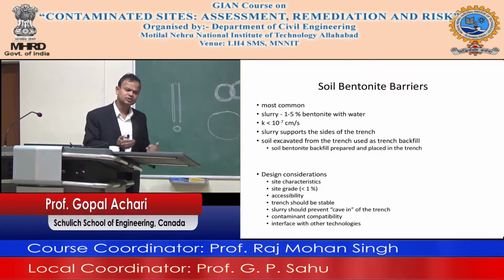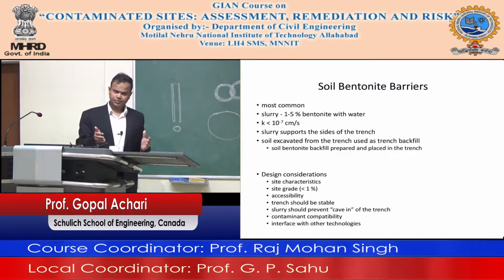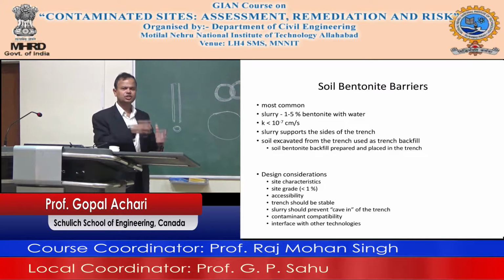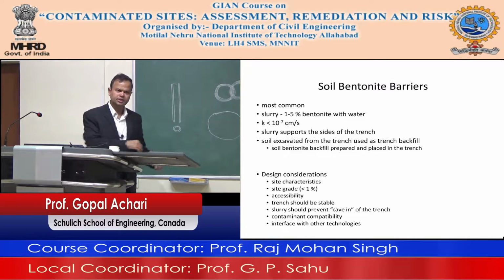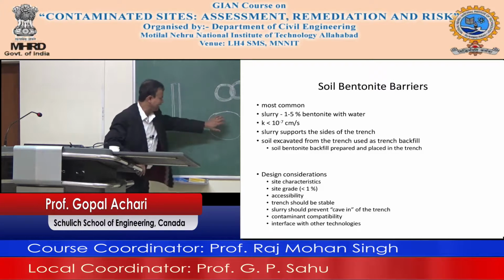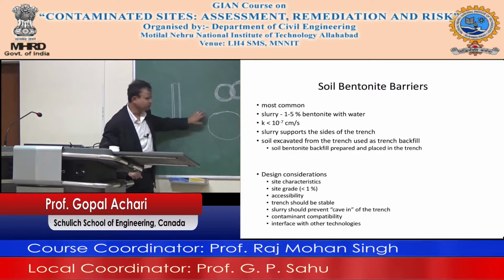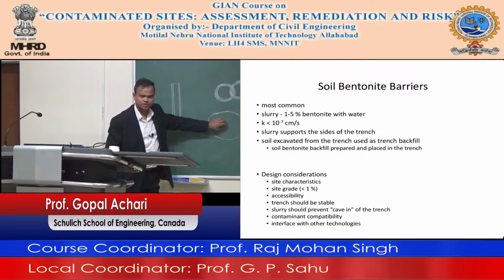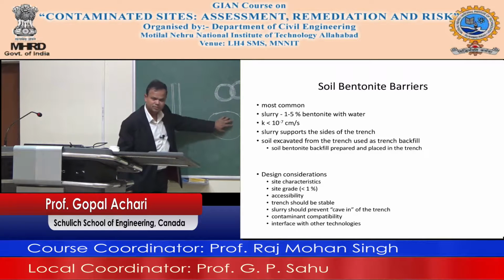So you may have a situation where the integrity of the cutoff wall is compromised, because of the reactive nature of the bentonite that's present there. If you are planning to put a cutoff wall which has bentonite in it, you want to make sure that whatever contaminant is present at the contaminated site does not react with it.